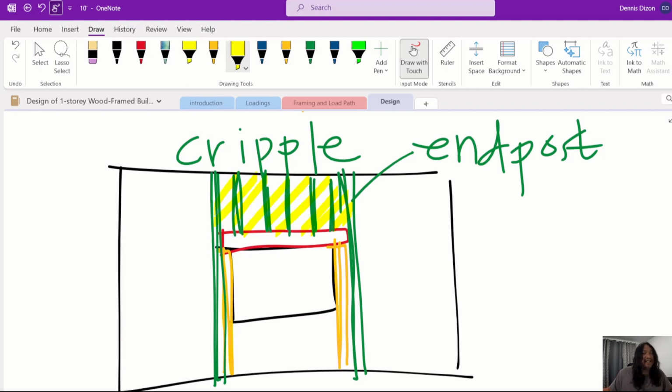Unless it is clear in the analysis or in the drawing that it has another support or that it is standalone. So if the bricks or the stone finish have separate support, then that's fine. You don't include those. Just include the actual wall assembly, including the finish.